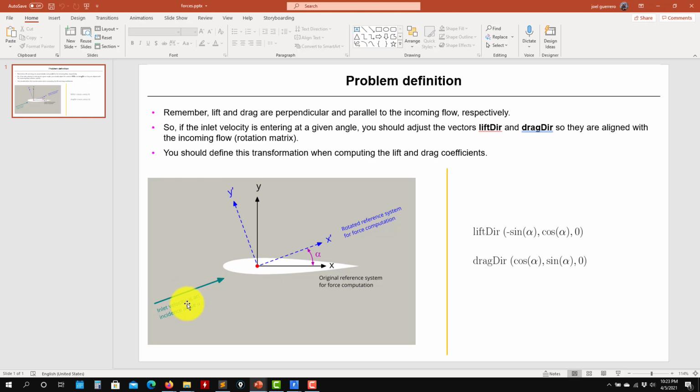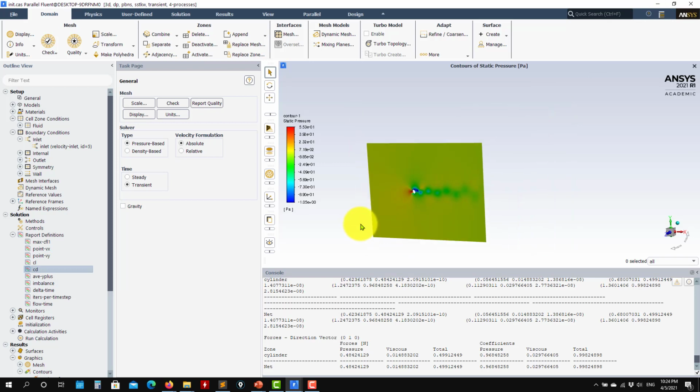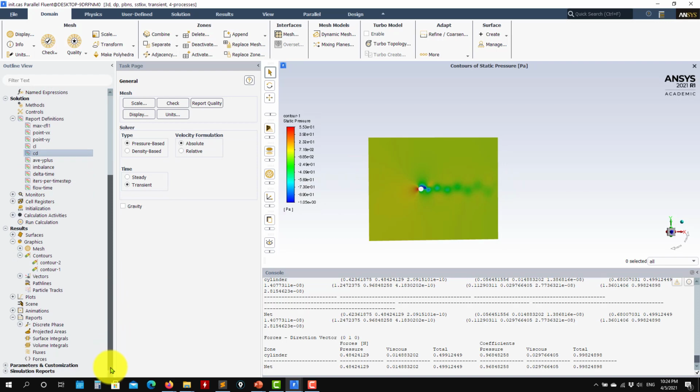I don't like to rotate this one because it also requires changing some other boundary conditions. In this case, for instance, if you rotate that one, you will change this one, but also here you need to give the inlet velocity and this has to become the outlet. So you have to be careful with that. That is the small warning that I wanted to give you.